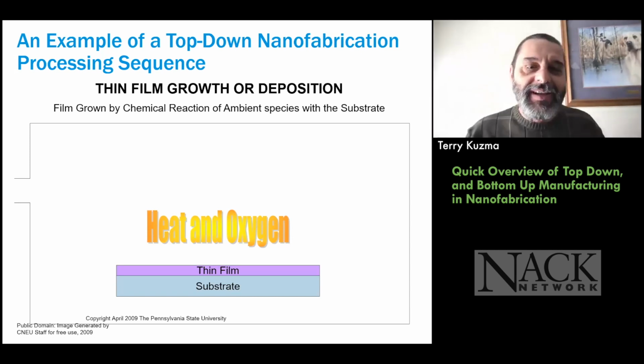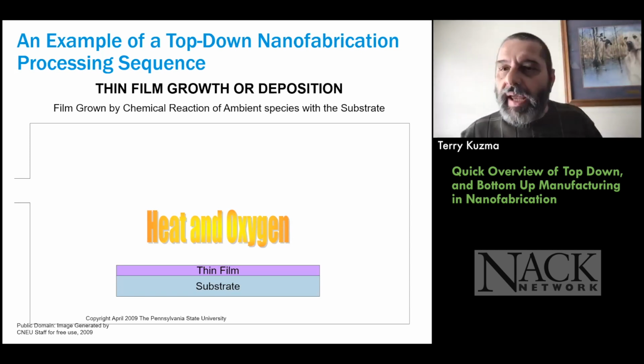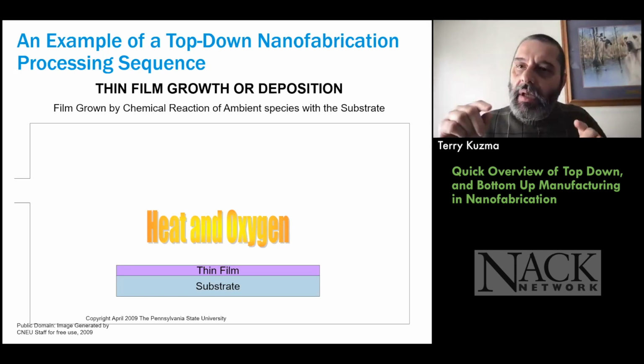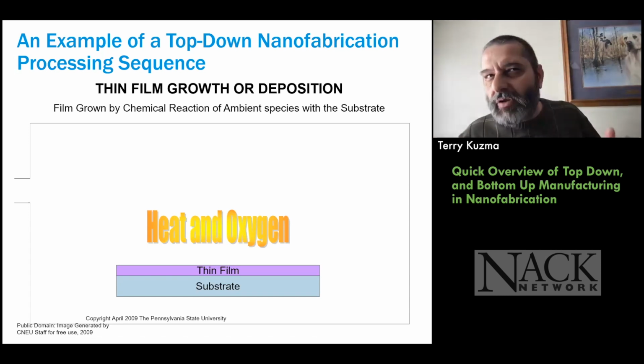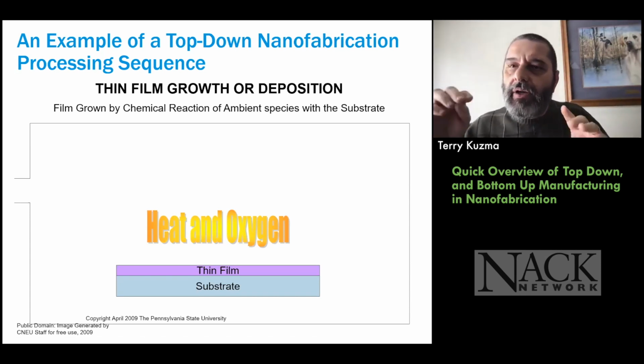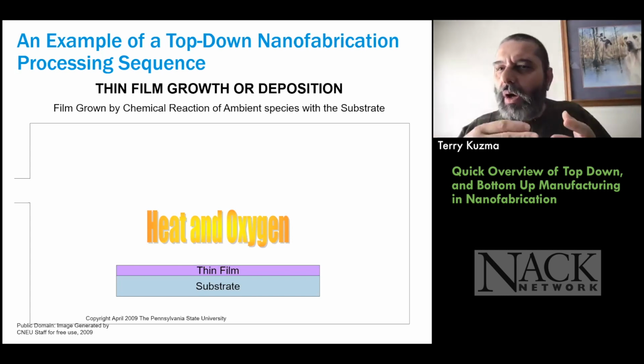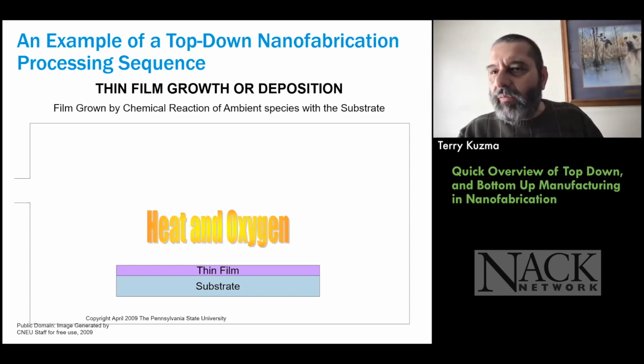So here's my thin film, and I apply oxygen, but oxygen would make a native silicon dioxide, but quit at about 40 angstroms or so, and it wouldn't have enough energy to diffuse and then to grow. So at room temperature, we wouldn't be able to get a good oxide film at that point. We need to have really high energy.